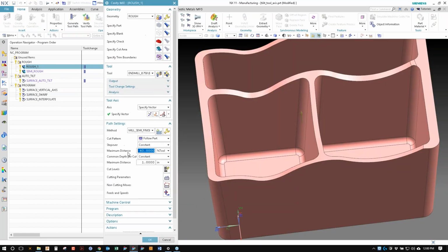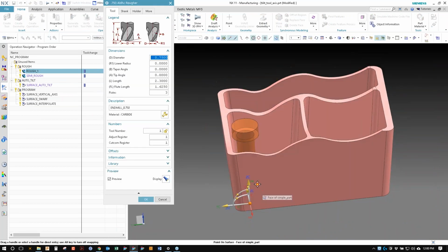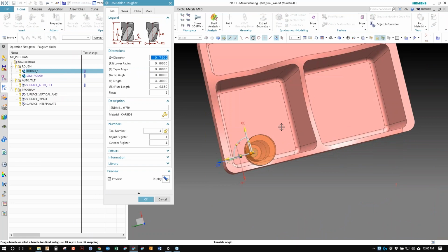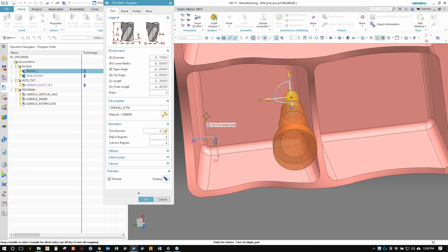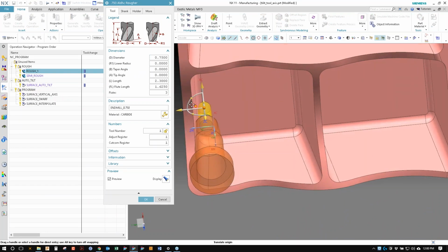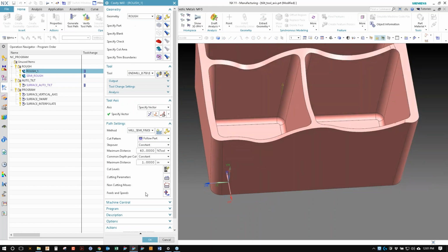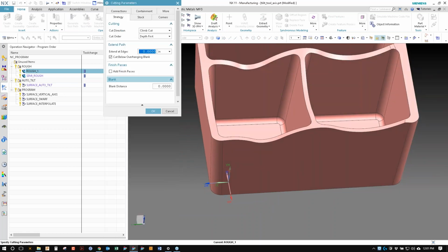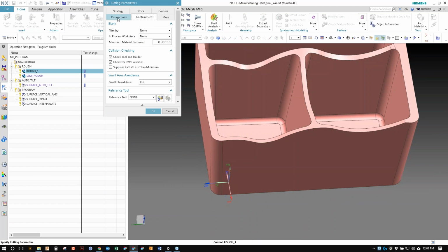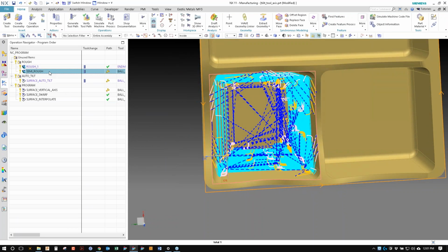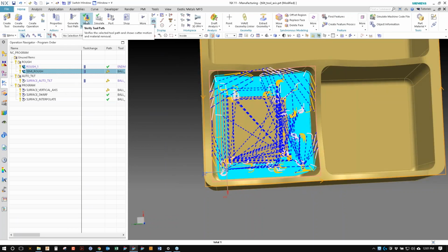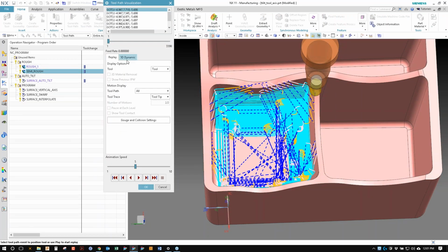So as the short end mill went down the tool path, it basically stepped in. I'll show you what that end mill looks like. So you can see it's short, and if you're down in the cavity, of course, it's going to hit the walls if it's roughing. Trying to get up near the wall, it's going to collide. But I had it basically using the cutting parameters, containment, and then just setting the amount that I wanted it to clear. It filtered that tool path and then left the steps. So then I did a rest mill, semi-rough, regular 3-axis, and then did the tilt.